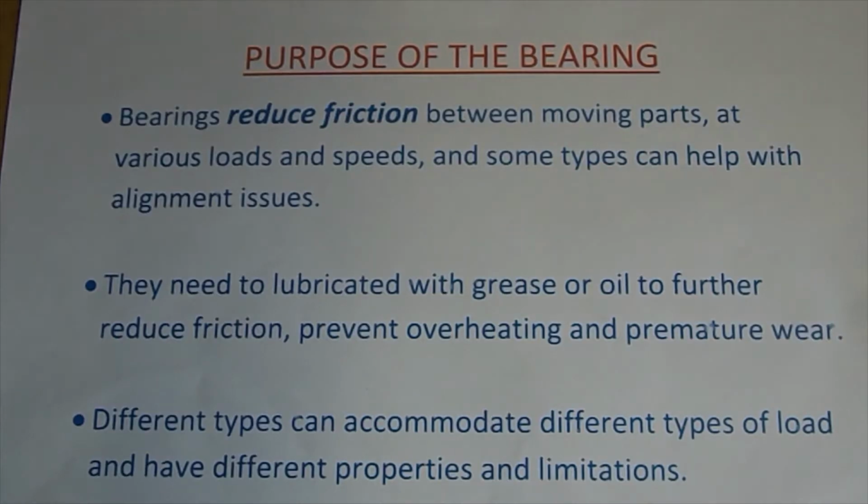Purpose of the bearing. A bearing is a mechanical component whose function is to guide a rotating assembly. They allow equipment to move at different speeds and efficiently transport notable loads while operating with minimum noise and vibration. They do this by reducing friction between moving parts. Lubrication, grease or oil, is used to further reduce friction and prevent overheating and premature wear.